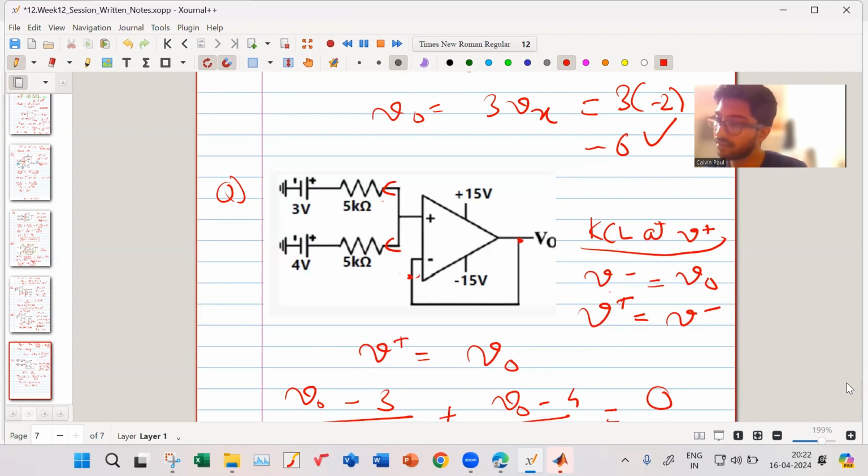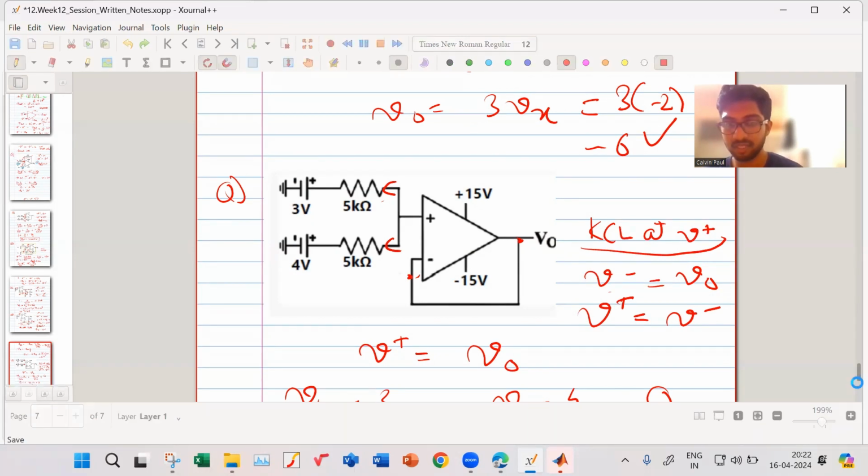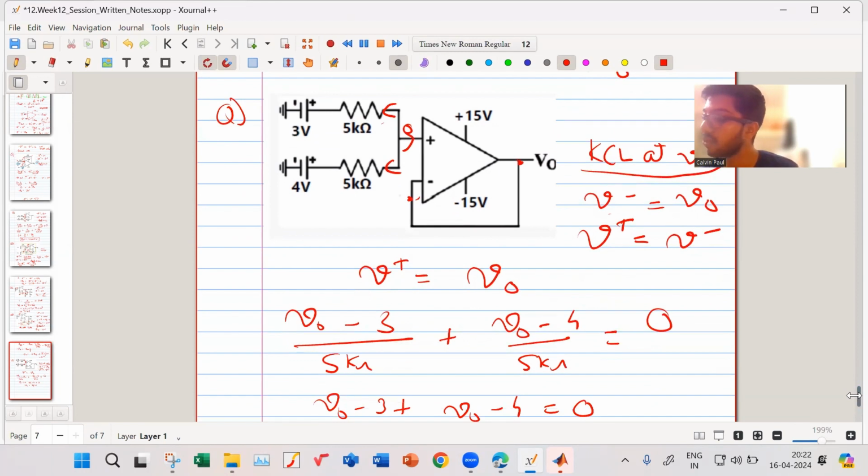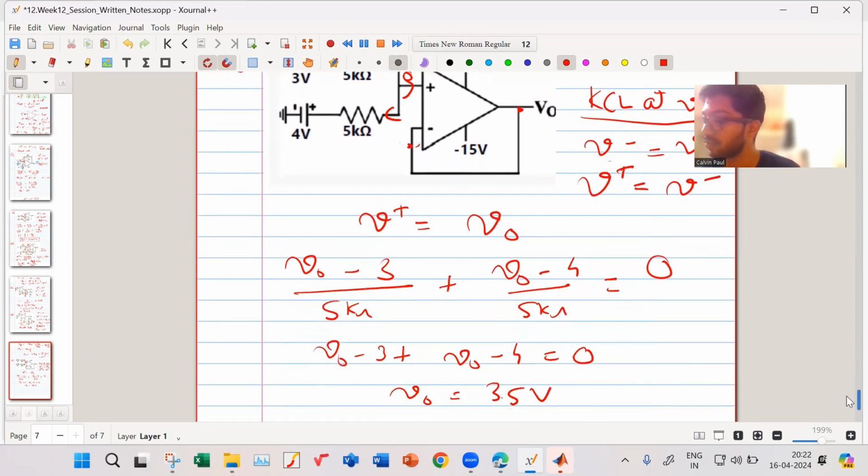One thing: in any network, it should satisfy KCL and KVL. That is something you must keep in mind, that it cannot be violated. So I apply KCL here, but I am ignoring this current. It is very minimal, it is 0. KCL is still true, and you must know what the assumptions are and what you have to do. But KCL and KVL cannot be violated.